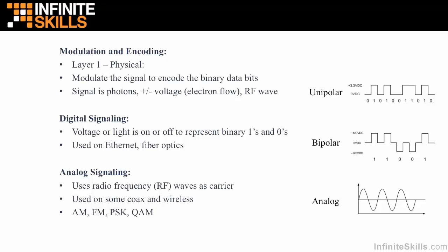Now I also can use something called phase shift keying, PSK, and this says where that one sine wave completes, if I continue upward as it's supposed to, as we see in the diagram, that represents no shift in the phase, and that would be a binary 0. But suppose I inverted that wave now 180 degrees.